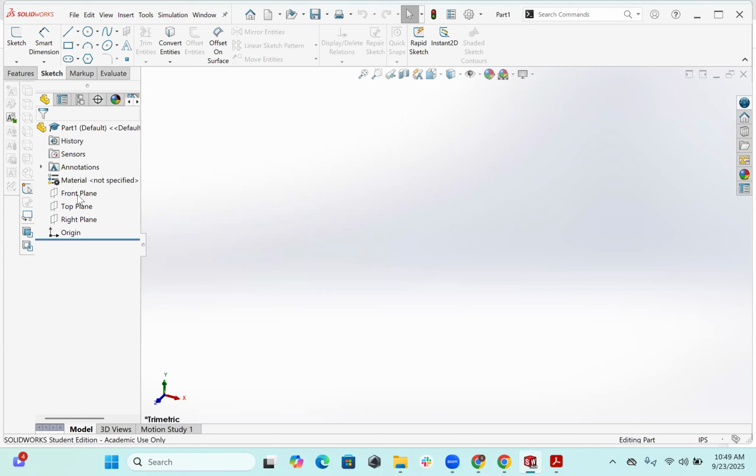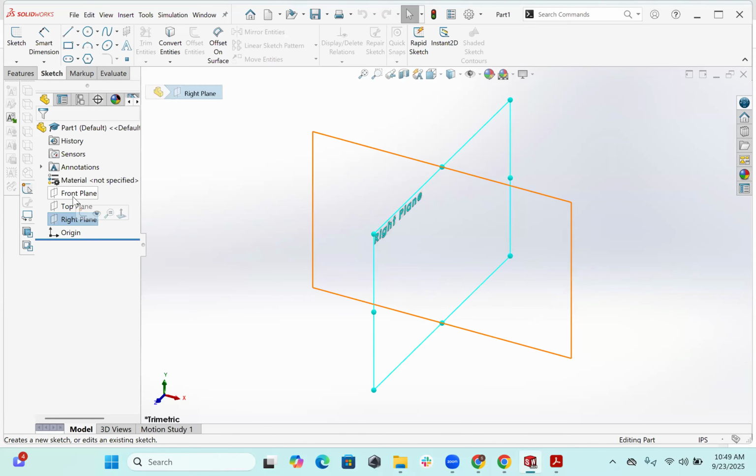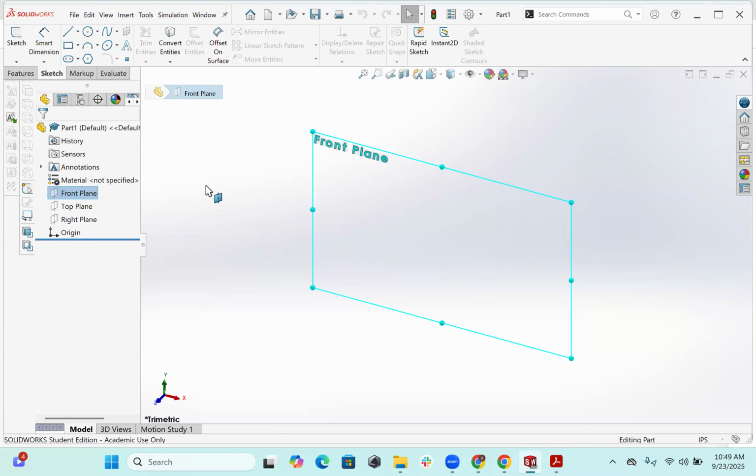All right, so now we're here, and we're trying to build this honey stick. We have to choose a plane to start with because we want this to be standing up. We can either go to the front plane or the right plane and sketch. So I'm going to start with the front plane. I'm not turning on all the planes, just to get used to this empty space so you can have room to work.